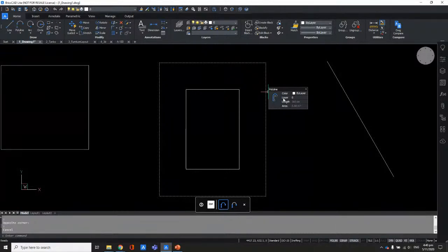And what is this icon that's being shown just on this part of this square that appeared on the rollover tip? This now is called the quad. We call this the quad cursor inside BricsCAD. The quad is an AI machine learning tool. It studies the way that you've been using your software. It also instantly recognizes that this is a polyline, and it suggests possible next tools and features that you may want to use, given that you're selecting this specific element or entity.